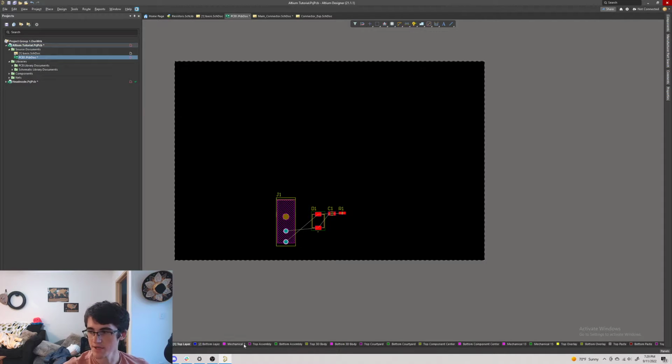So you'll notice at the bottom here, there are different layers. And so PCBs have multiple layers that you can use planes with, which act as giant areas that hold the same signal or power source or reference. So by default, Altium will create a 2-layer board. On Prism, we either have 2 or 4-layer boards depending on how complex they are and how many different signals they have to manage. You can do more than that too. The price goes up with the more layers you do, so at some point it can get redundant if you aren't doing a lot on the board, but sometimes it can help clean up a lot. And if you want to see that, I have some other videos on that too.